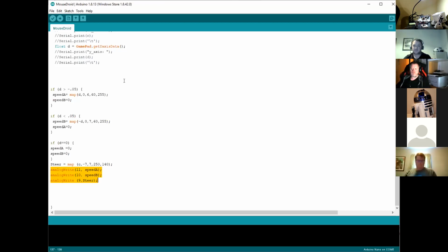Yes. So on the Arduino, the I/O pins, the pins that write out, there's 2 different types. There's a digital, which is 0 and 1, so that's on or off, and then there's an analog, which basically does PWM, pulse width modulation. What it does is it allows it to go from virtually nothing coming out to quite a big wave, if that makes sense. So the PWM signal on the pin in Arduino world, 0 is 0 and 255 is max. So that's limited more by the actual Arduino.